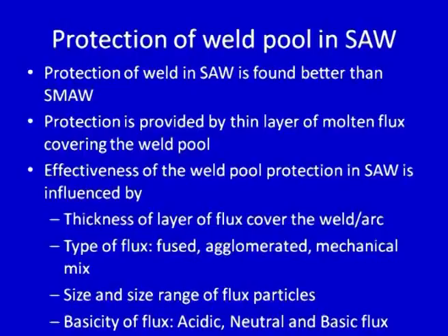So, agglomerated fluxes taken from the bottom of the store will be of different composition as compared to those at the top. This variation in composition of the agglomerated fluxes also results in significant variation in the effectiveness of the protection provided to the weld pool